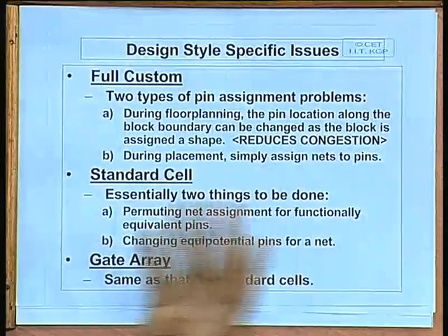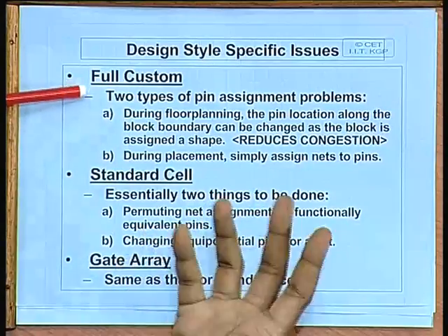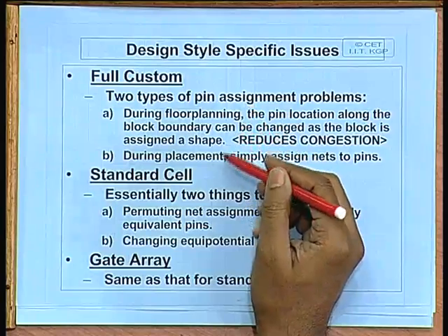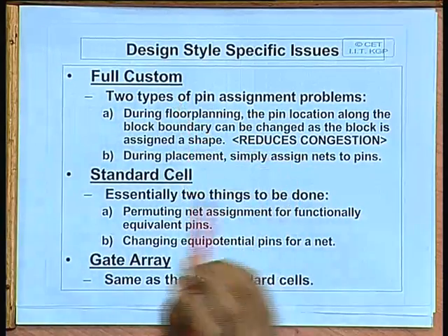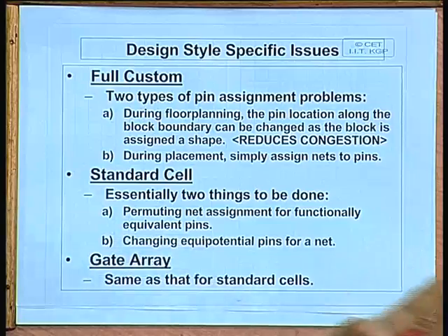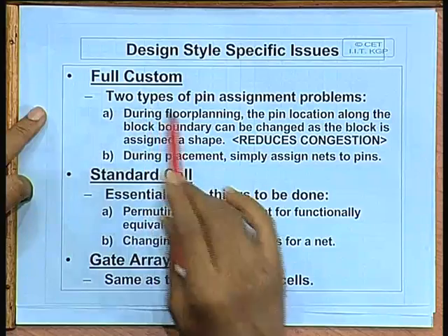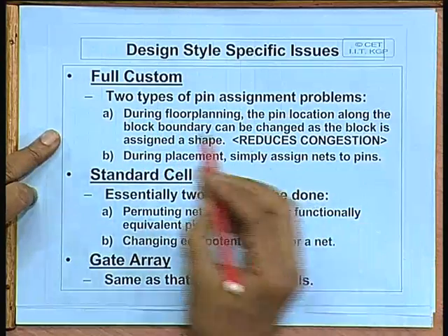Now, let us look at some of the design style specific issues for pin assignment. Well, for full custom you have entire flexibility. There will be many blocks which may be flexible, which are not already pre-designed. So, you have the flexibility of assigning pins on the periphery. So, full custom design style exposes the complete range of the things you can do during pin assignment. But here normally you do it in 2 different steps.